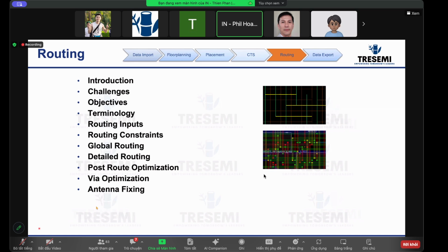During place and route, you have import, floor planning, placement, CTS, routing, optimization, post-CTS optimization, all the steps that you listed here on the top of the page, right? It's floor planning when you start looking at timing. Should check from floor planning, right?